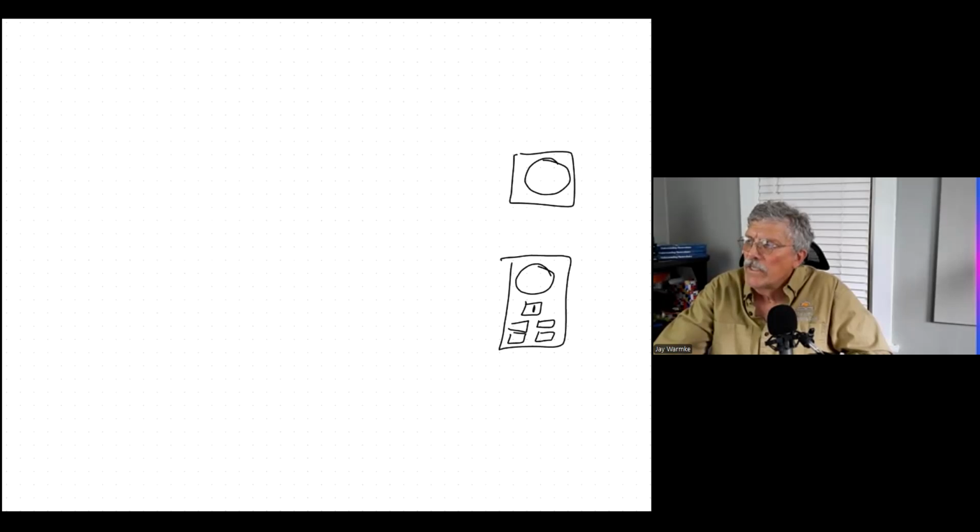So any new installations now have to have something that looks like this, where there's going to be this emergency disconnect at the meter. It's going to be closed, but now when the first responders come, they're just going to open the door and flip the switch to off. So now they're just going to disconnect you from the array just by flipping a double pole breaker, just like the main in your circuit breaker box. So that's good. It's on the side of the house.